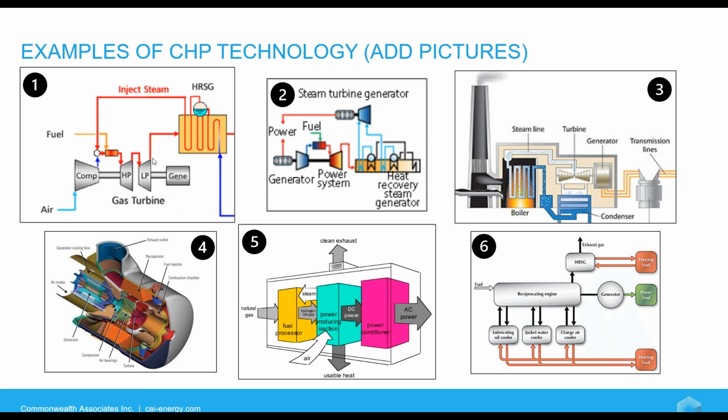You have the gas turbine, right? Its exhaust is going to heat up the HRSG water and you'll produce steam. Number 2 is the same system. This is the CTG with HRSG with the steam turbine generator. You're adding the second generator, so it'll take the hot water and the steam from the HRSG, and then that will also propel the turbine and produce more power.